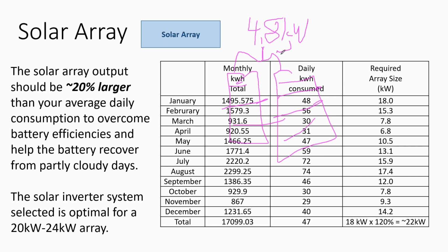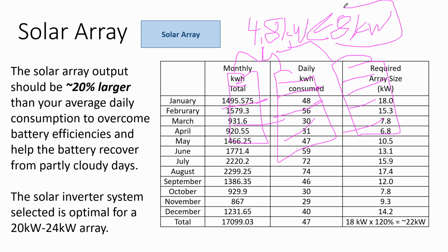But we actually ended up doing 3 circuits of panels and putting around, I don't know, 8 kilowatts of solar onto this 4.8 kilowatt charge controller, because we didn't need all 8 kilowatts to be working in spring or in summer. What we needed is that 8 kilowatts to be working on the cloudiest day in the winter, at which point we were getting not even up to the output capacity of the system.